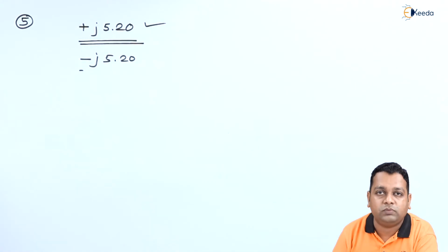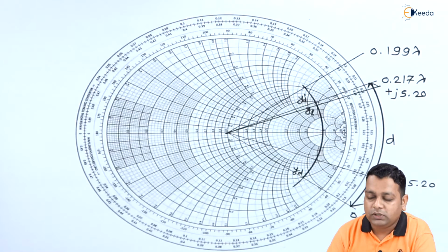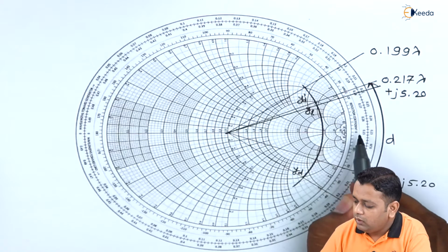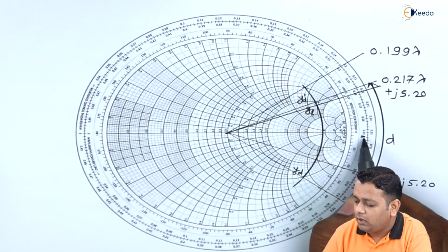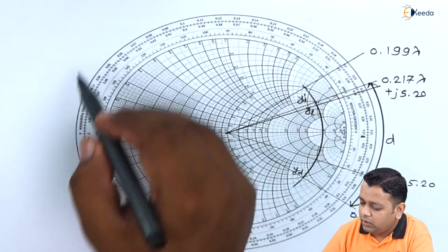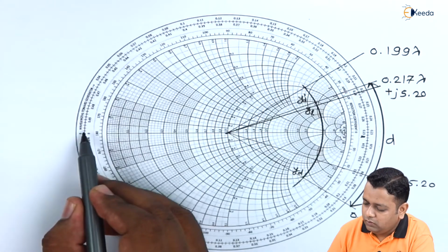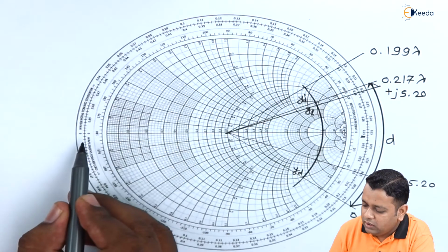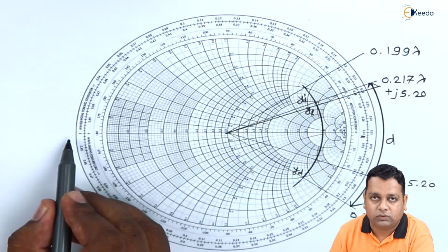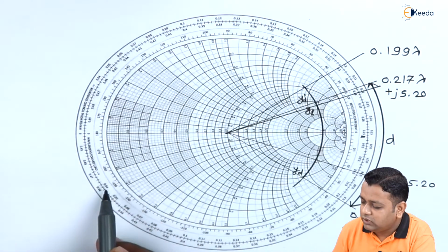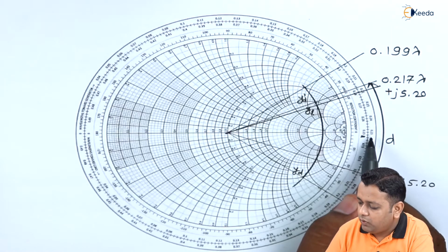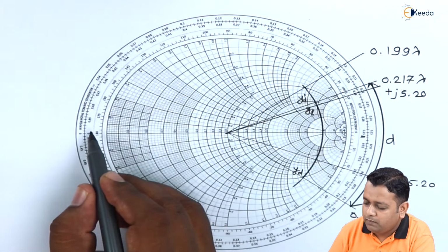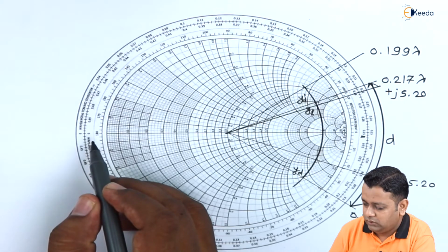So getting back to the Smith chart here. On the Smith chart, here we have this to be 0.25 times lambda, and for one complete cycle, if you go in the direction towards the generator, here it will be 0.50, or from the wavelength towards the load, if you take the direction, here you will be at 0.25 and again completing this one cycle to 0.50 here.